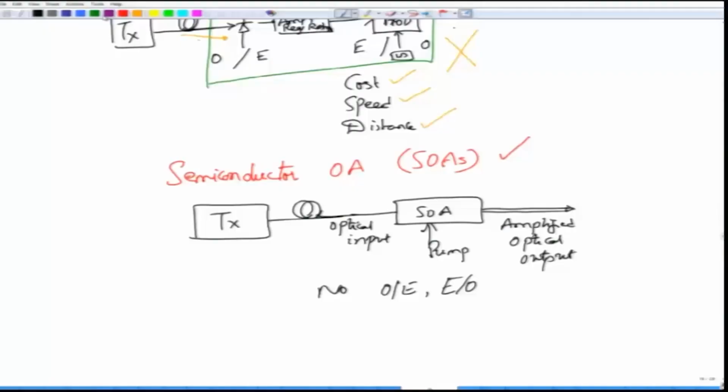So, if you were to follow how the optical power would go, let us say you launch a certain power Ptx over here. This is the launch power, maybe you could call this P in, but I just arbitrarily call this Ptx. Because of the fiber, there is a linear attenuation, correct. So, the power basically goes down. I am plotting all the powers in the dB scale, and what is the loss here? Alpha f into L. So, the slope of this one would be alpha f. At this point, of course, the power that you are receiving will be Ptx minus alpha L, all measured in terms of dBm, that is, how many milliwatts above a reference.